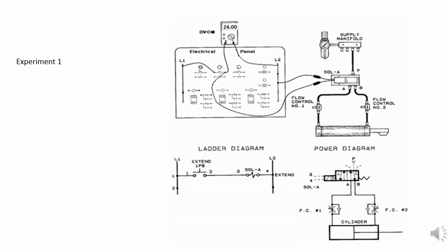Second connection is made toward the solenoid, where we have a DCV that has 4 flow paths, 2 positions, and is pilot operated but solenoid controlled. So when solenoid A is energized, that solenoid energizes the pilot, and this causes the valve to shift. Now it only has 2 positions, so the normal position in the diagram is the one on the right where the spring is attached. So if you energize that solenoid, the other envelope will be the flow pattern, and then if the solenoid is de-energized, then you go back to the envelope that has the spring attached on it.